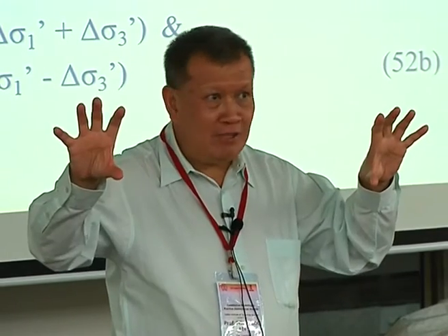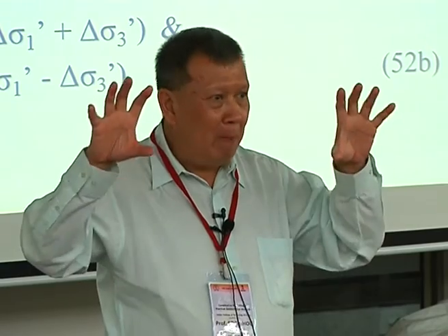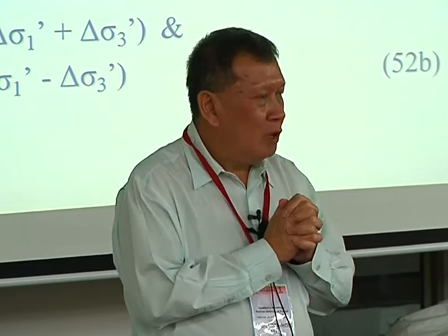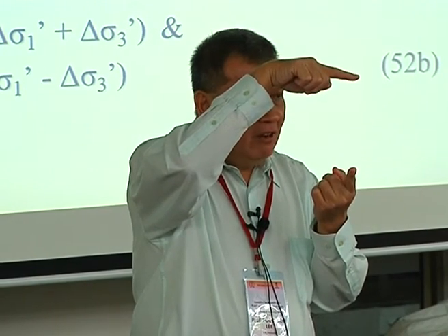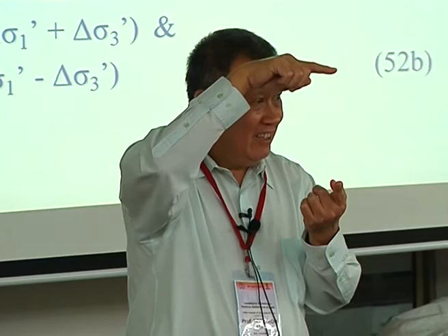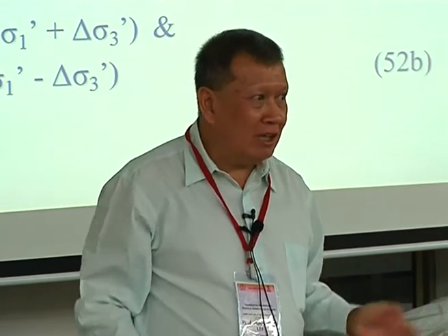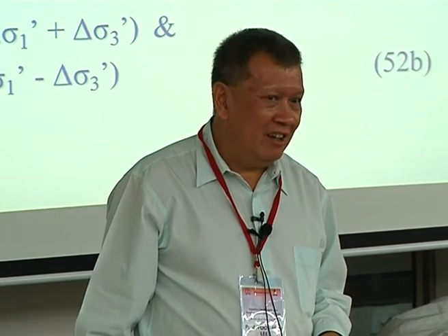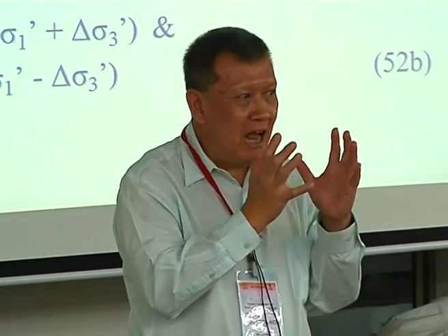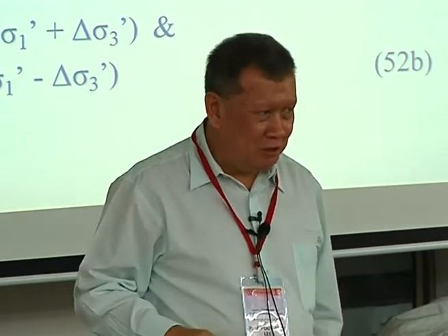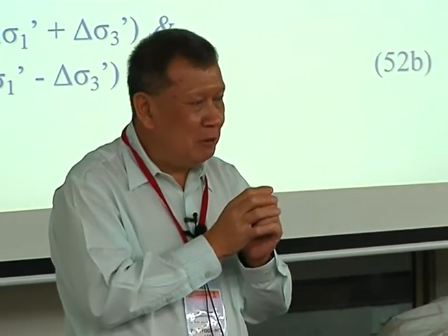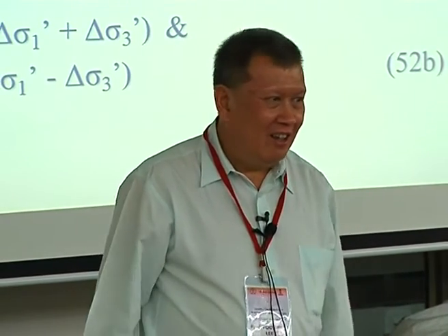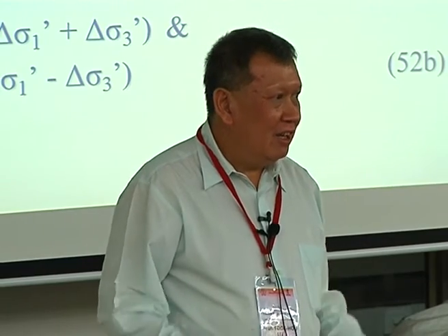The two circles are offset by the amount equal to the pore water pressure, but the size must be the same. And it all has to do with the fact that the radius of the Mohr circle is the largest shear stress the sample is experiencing. And we all know water cannot carry shear stress. So total shear stress is the same as effective shear stress. Correct? Anything related to the size of the Mohr circle has some relation to the shear stress. That's why in an isotropic stress situation, there's no shear stress. Mohr circle is a dot. See? That's why it's all related.